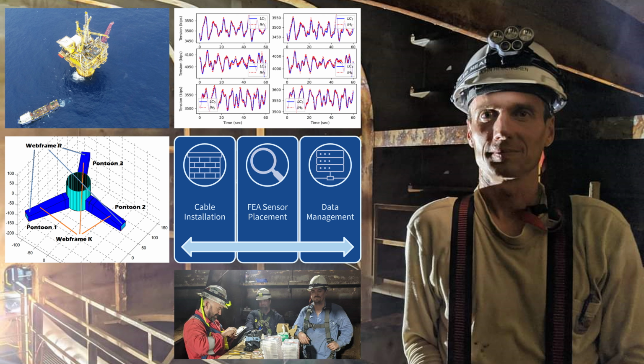Now, one of the things that we saw when we turned it on is that there was a big discrepancy between those engineering calculations and the actual values. First of all, we asked ourselves where did we go wrong, and found out that we had made some critical assumptions that were not correct about the finite element analysis. And so then we took machine learning methods and did regression with the few remaining load cells that were still there. And we were able to come up with very good models.